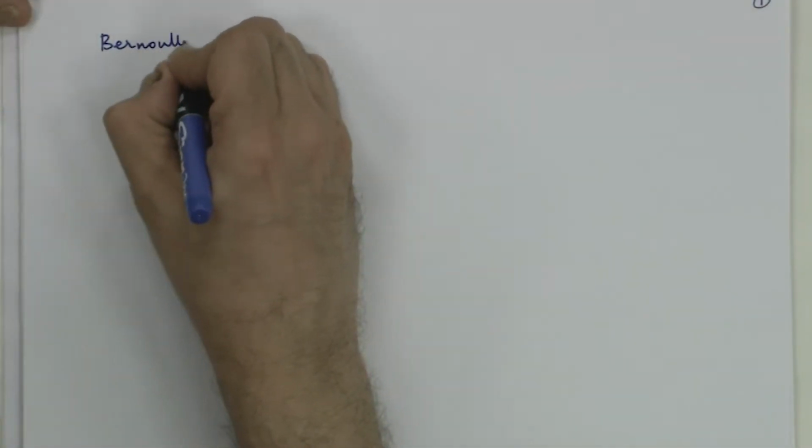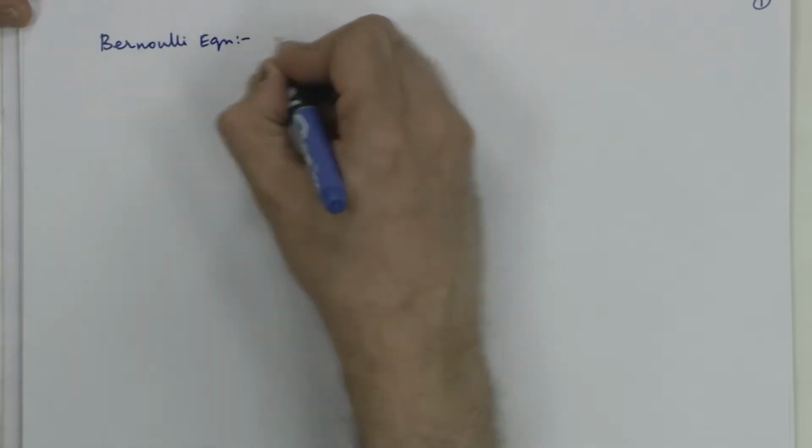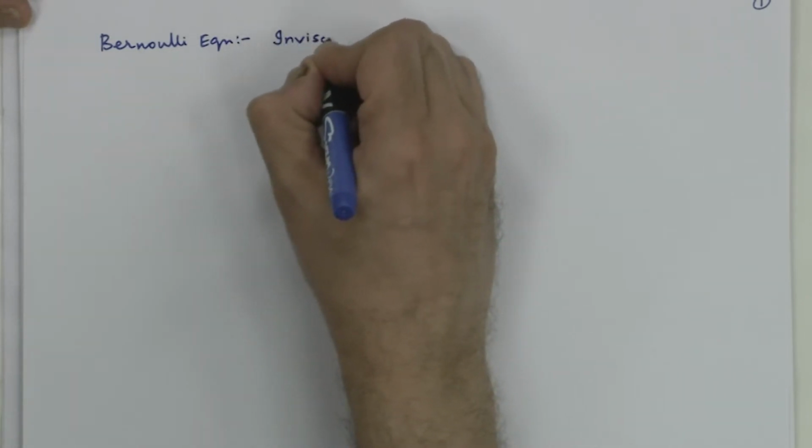Good afternoon. Welcome to this lecture on fluid mechanics, and the topic for today's discussion would be introduction to boundary layer theory. Now, in the last so many lectures on fluid mechanics that we have had, we stopped with Bernoulli equation, and we also had some exact solutions for the Navier-Stokes equation, right. Bernoulli equation essentially was inviscid flow. There were several assumptions that we had, and one of the primary assumptions was steady inviscid irrotational flow.